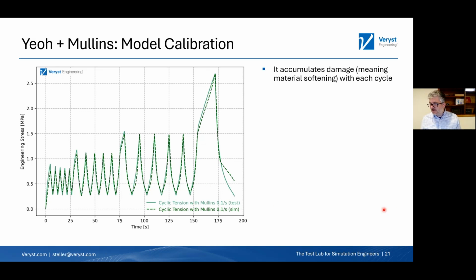What's the best way to check model stability in terms of mathematical check, physical meaning, and potential overfitting? So Drucker stability is what you're asking about. I believe Ansys does a check for you when you're talking about a hyperelastic model. I believe that's output in the .out file, but I'd have to check. That's generally how I do it. But to the question earlier about different test modes, if you're not using a Mooney-Rivlin model or something that uses an I2 dependence, generally you're pretty safe, and I wouldn't worry about that too much.